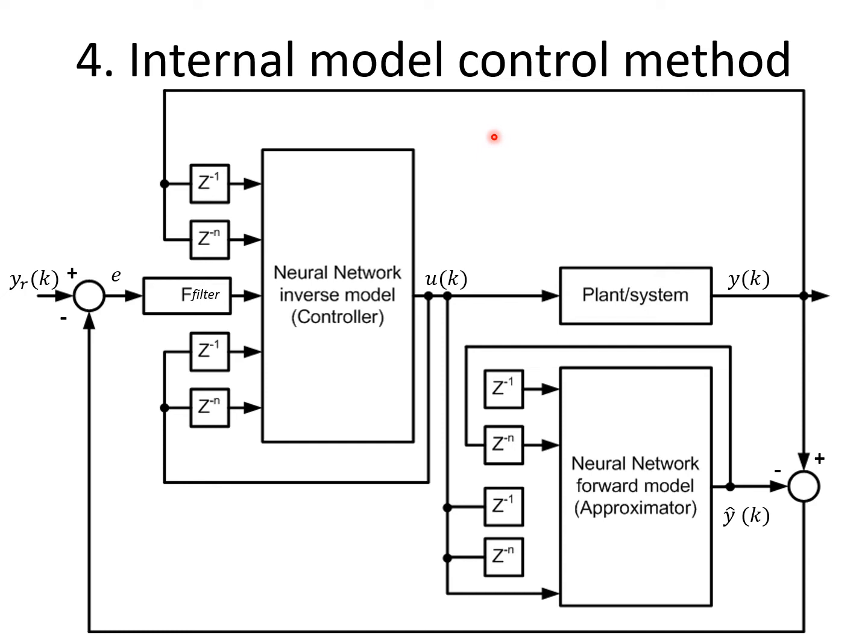As you may have mentioned before, for linear systems we've got the PID to always work, but for non-linear systems it's difficult. We need to implement these advanced methods, and AI methods are one of them, and it all depends on how good you get your controller, and how good the controller is depends on the steps that you follow in obtaining the models, for the forward model or the inverse model. But since this is a controller, the inverse model or the controller becomes more important. It is the main criterion for making this whole control strategy work properly for us.